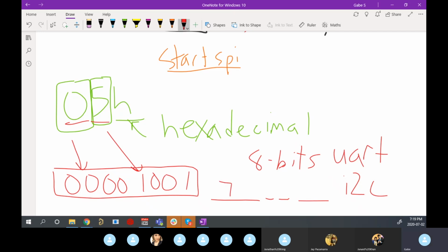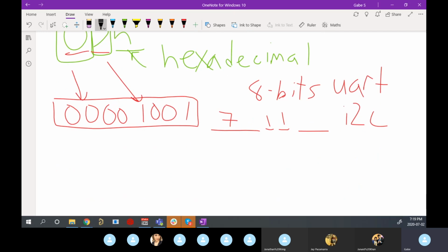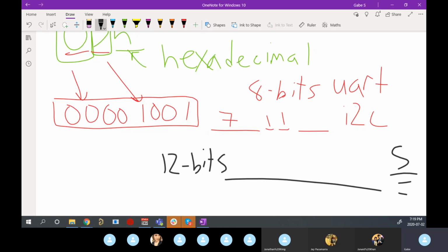This was this whole complicated thing for I2C. But in SPI, it doesn't matter. I can just send 12 bits of whatever I want, which is really cool. There's no addresses, there's no ACKs, there's no read-write bits, there's none of this. As long as your slave knows what you're doing and your slave is asking for this stuff, then you can just send whatever formats you want.